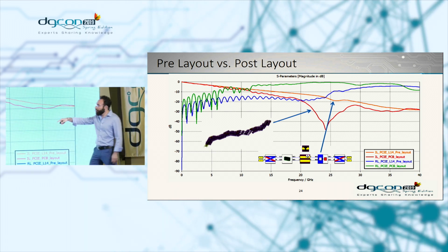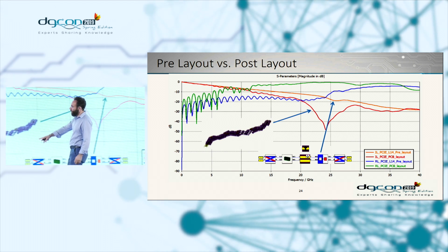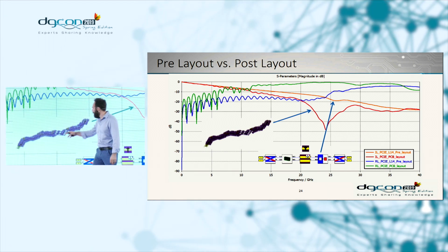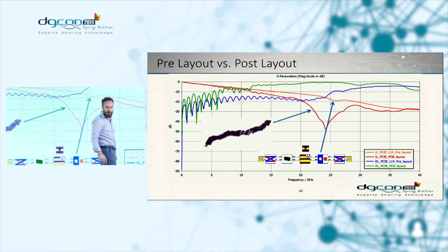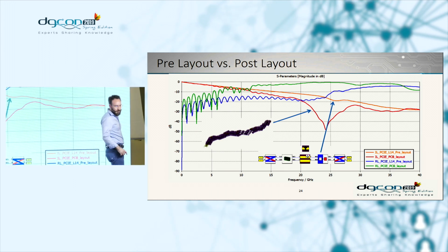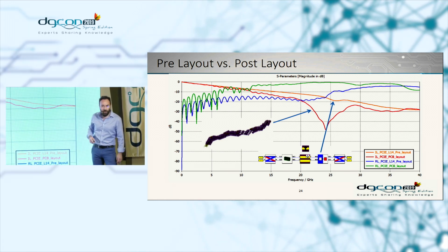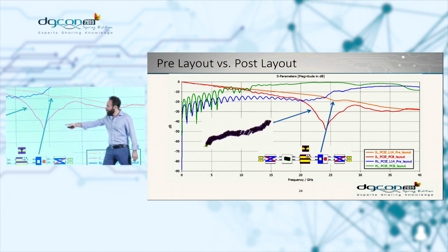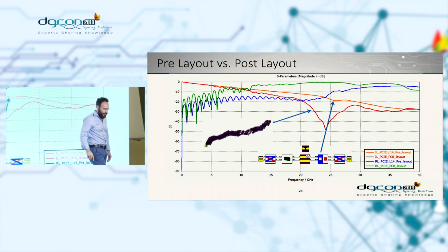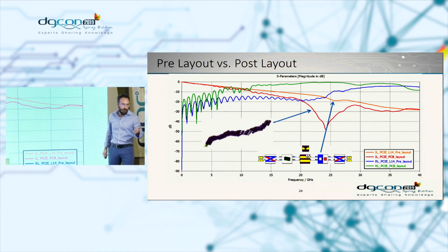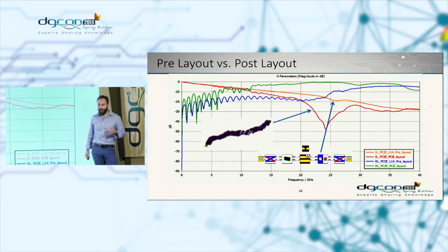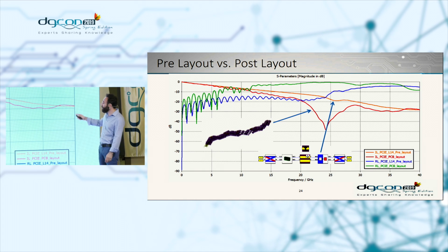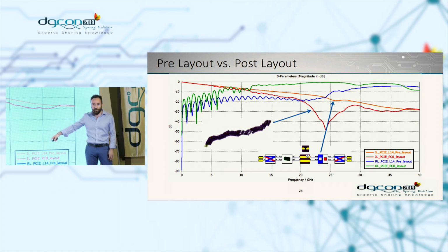This is a complete net, starting from one side of the connector and ending probably in the middle of the PCB, or close to the active component. As you can see, this generates a resonance, mainly due to the extra capacitance, due to the net, due to the geometry, due to a lot of things, including the IBIS file that we put at the end.